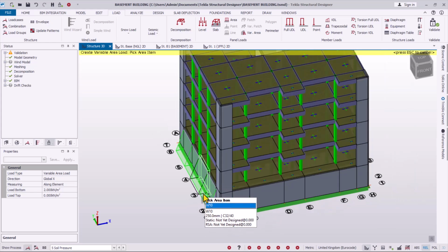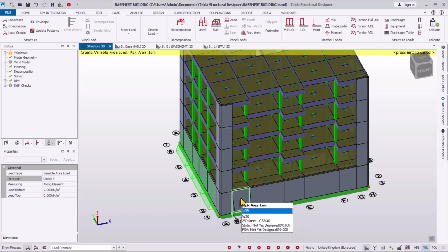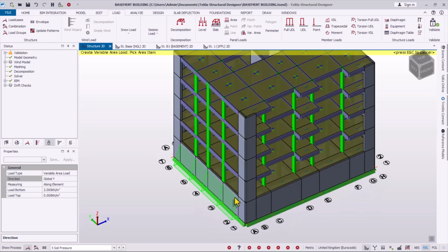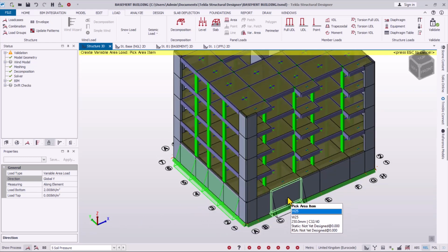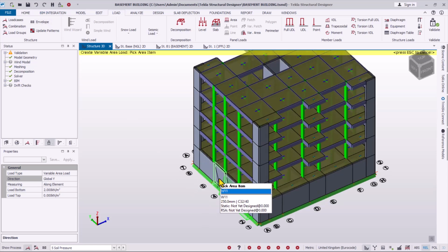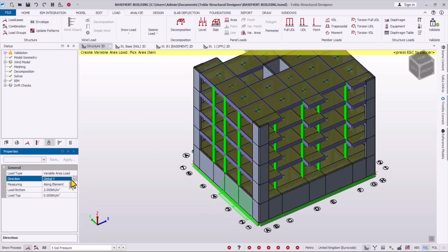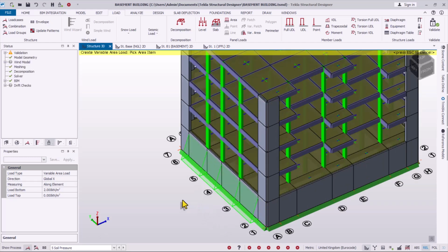Okay, so I've done that. I can now change the direction to the Y direction. This is the Y direction, so I can place it here as well. But this is being placed from the inside because of the direction of the UCS icon. It is supposed to be placed outside, but it is placing inside. So what you do is undo the first, undo the second. This has been removed from here, so change this as well, the X direction, and then apply this again, just like this.